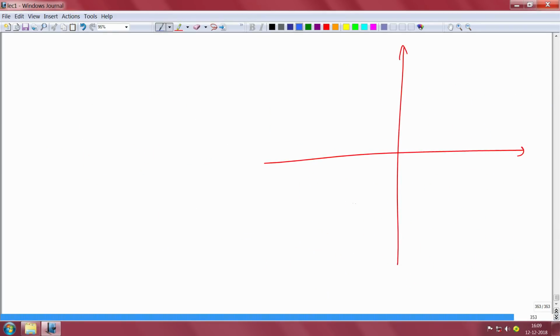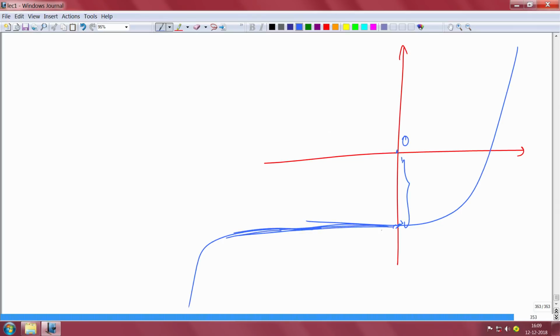So you will have the same sort of IV. This is your IV, and this is your zero bias current. Even at 0 voltage you will get some current, and eventually it will break down. So the current is mostly flat. Slowly it might increase if your sample is leaky, but that is okay. This is a dark current.